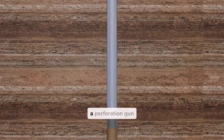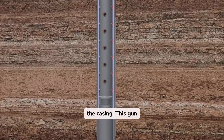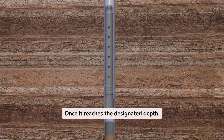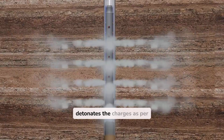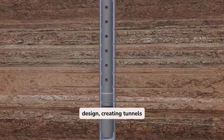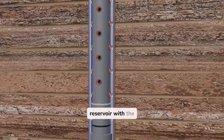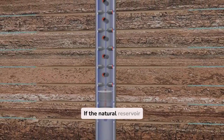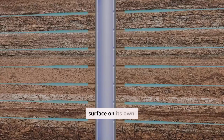For this purpose, a perforation gun is lowered inside the casing. This gun is equipped with multiple small explosive charges. Once it reaches the designated depth, an electrical signal from the surface detonates the charges as per design, creating tunnels through the casing and cement wall to connect the oil reservoir with the wellbore. If the natural reservoir pressure is sufficient, oil will rise to the surface on its own.